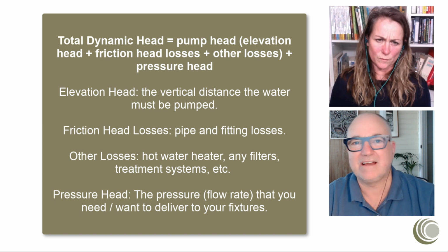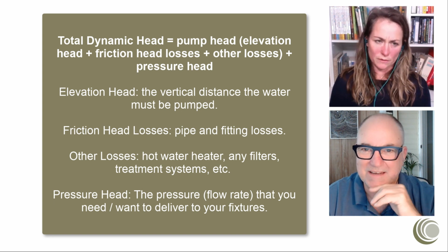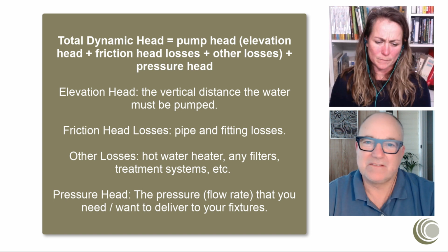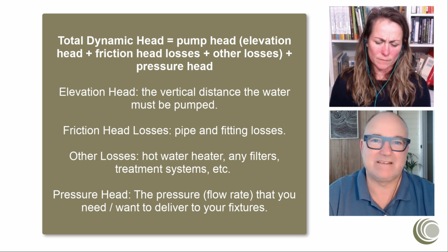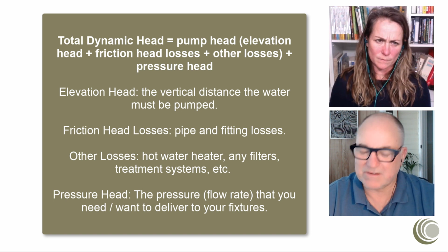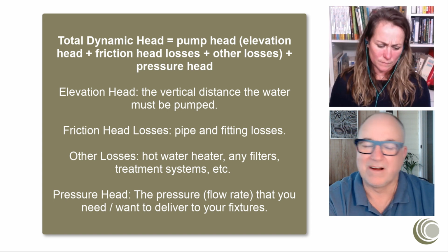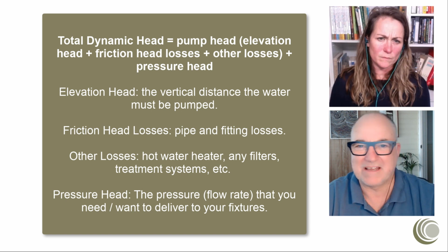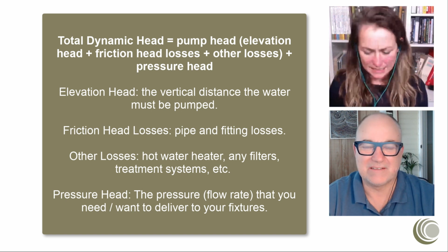So you go, okay, I've got 27 meters of head. Yeah. And you say, oh, I'm okay because my toilet on the third floor of some building is 27 meters above my pump. I'll be all right. Well, no, you won't, because there'll be zero flow rate and zero pressure by the time the water gets there. Right, and that's the thing to understand, right?